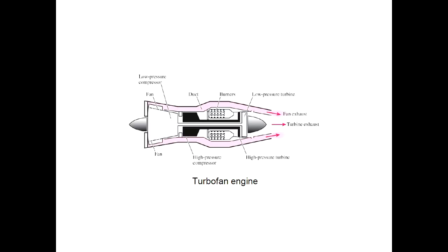If you have a turbojet, what should be the bypass ratio? Yeah, it should be 0, right? So if you have a small bypass ratio, this engine is still more or less like a turbojet, which means it still can fly at high speed, and which application requires high-speed flight? Fighter jet. Yep.